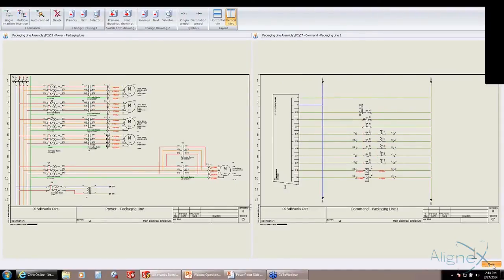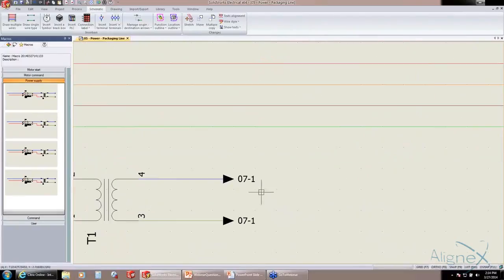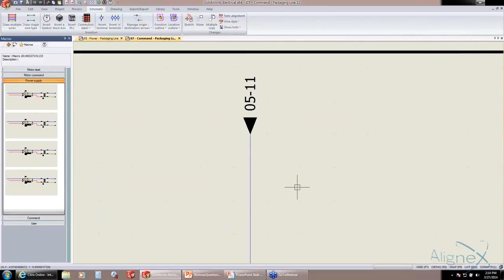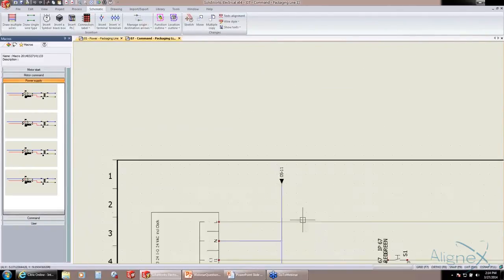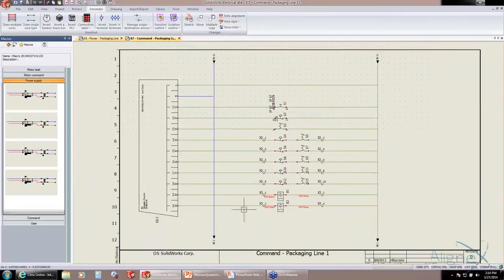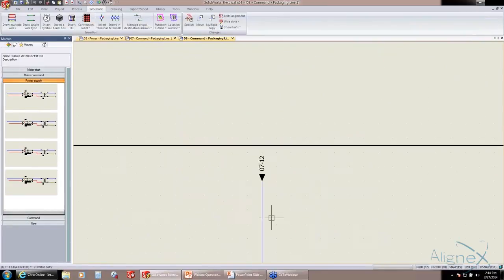With our connection set, it shows my page number and row number where the connection is. These are editable. There is flexibility in the formula that defines this for different scenarios. I can right-click on that, go to, and it'll take me to that page. And then we can zoom that page, okay? And we can continue to track down through our schematic following our connections and our circuits from page to page.